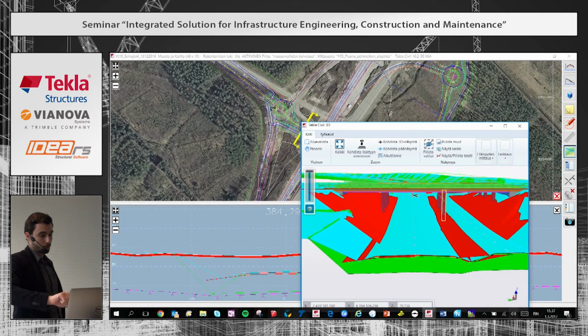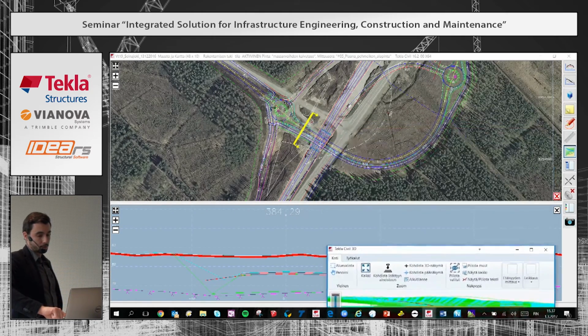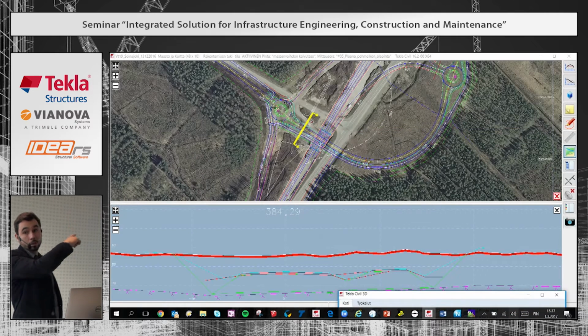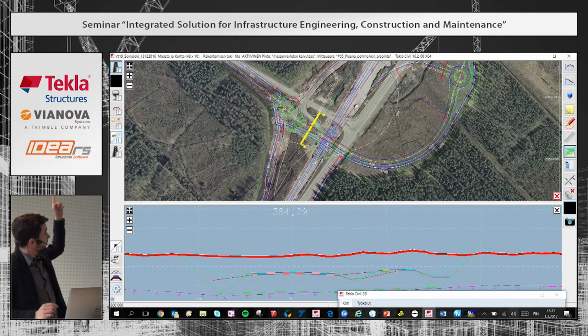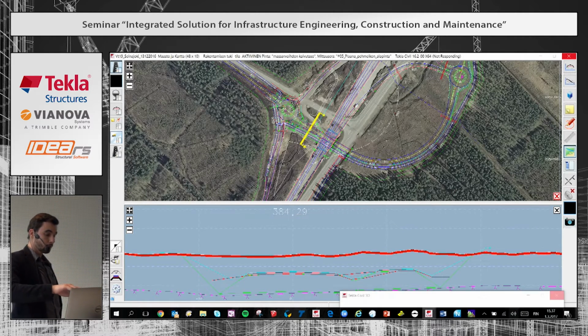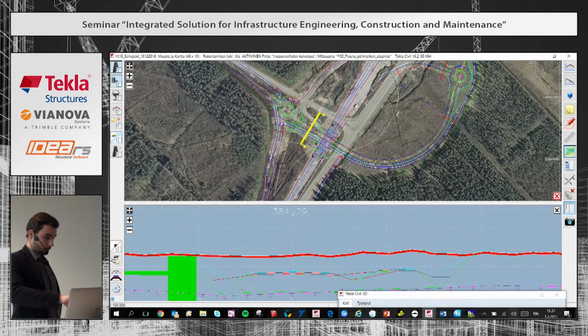Usually what the users do, they mostly use these two, cross-section and the map. Of course, here I have the road models, but if I also have pipes and manholes, I just push that button to make them visible in all the views. And once I have them visible, I can then ask about information.